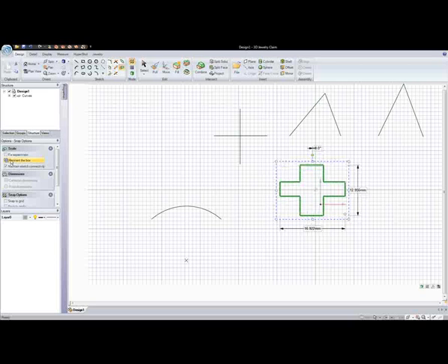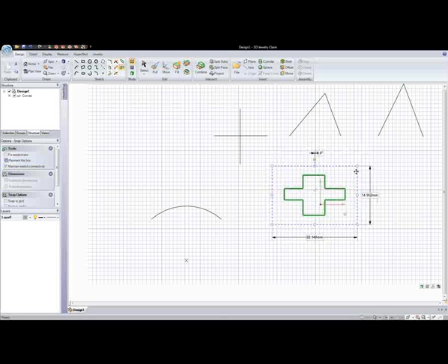We also have reorient the box. By selecting on this, you can reorient the box without altering the design. Once you alter your orient box, you can turn it off, and now you can alter your design accordingly.